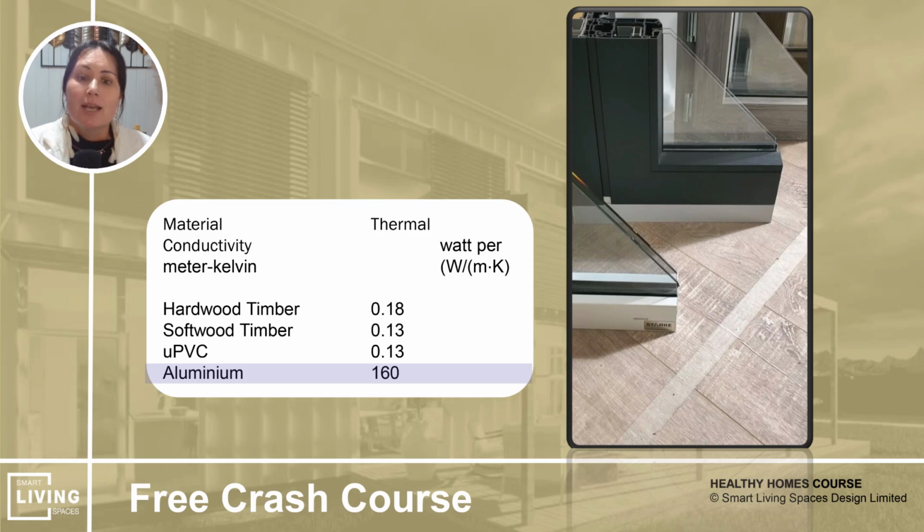If it's timber, sometimes you might need to just replace the whole unit. Now, we have three common materials for windows on the market: timber, UPVC, and aluminium. In November 2023, legislation required all aluminium to be thermally broken. That's with a plastic piece in between two aluminium skins, and at a minimum double glazed with high performance glazing.